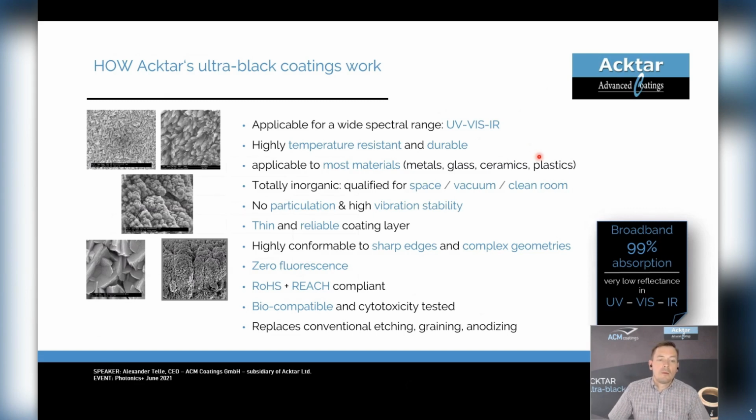What is special and really helpful in different optical applications is that we are able to conformably coat sharp edges and complex geometries. And that helps, for example, with baffles, vanes, and apertures, even pinhole apertures, where we are able to apply the coating. The coating is relatively thin, nominally 5 micrometers for the visible and near infrared wavelength range. And it's RoHS and REACH compliant, and this won't change in the near future.